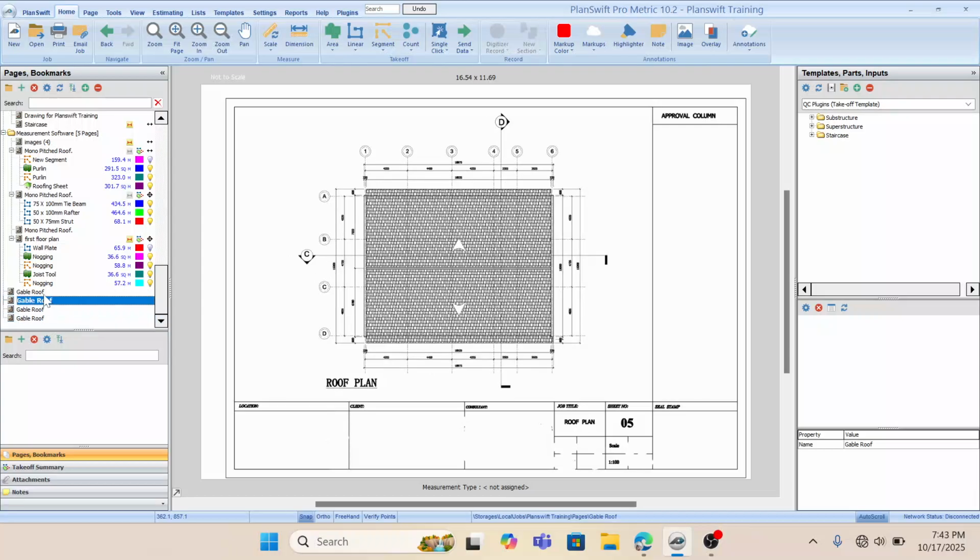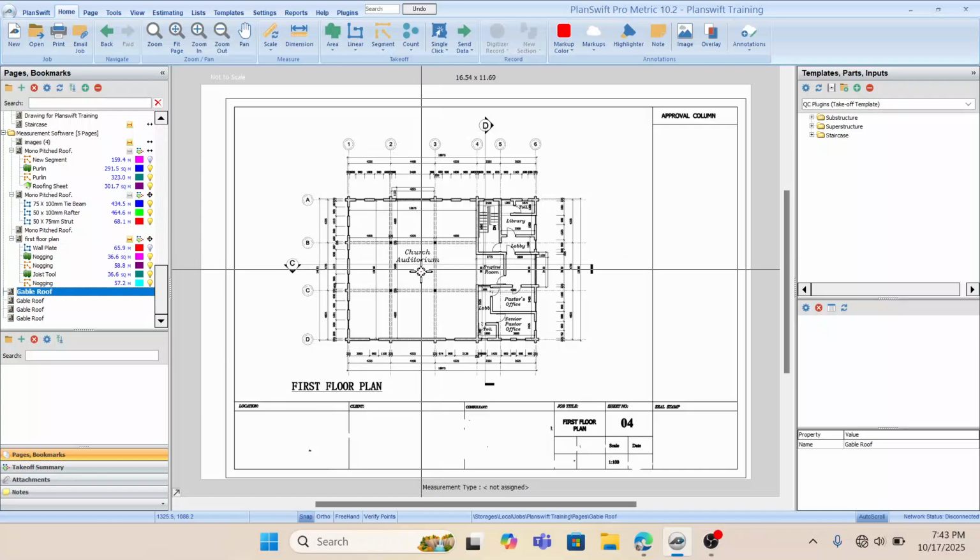From this roof section, what we have here is a slope in 2 directions. This direction, and the other direction. So we have our setup of rafter, tie beam, king post and struts arranged in this direction, at 1.2 center to center, while our purlin will span across the length of the building.